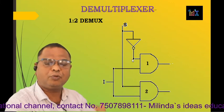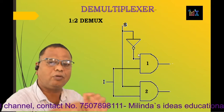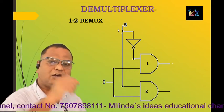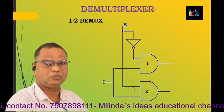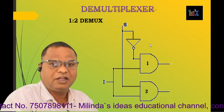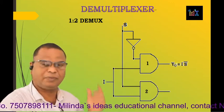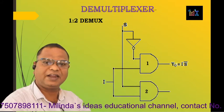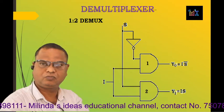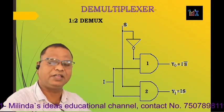The control input connected to the first AND gate is connected through a NOT gate, so it is the complement of the control input. While for the second AND gate, the control input is directly connected. Hence, the output of the first AND gate, that is the upper AND gate, is given by Y0 is equal to I S complement, while the output of the second AND gate is given by Y1 is equal to I S. So that is the logic diagram of 1:2 demux.